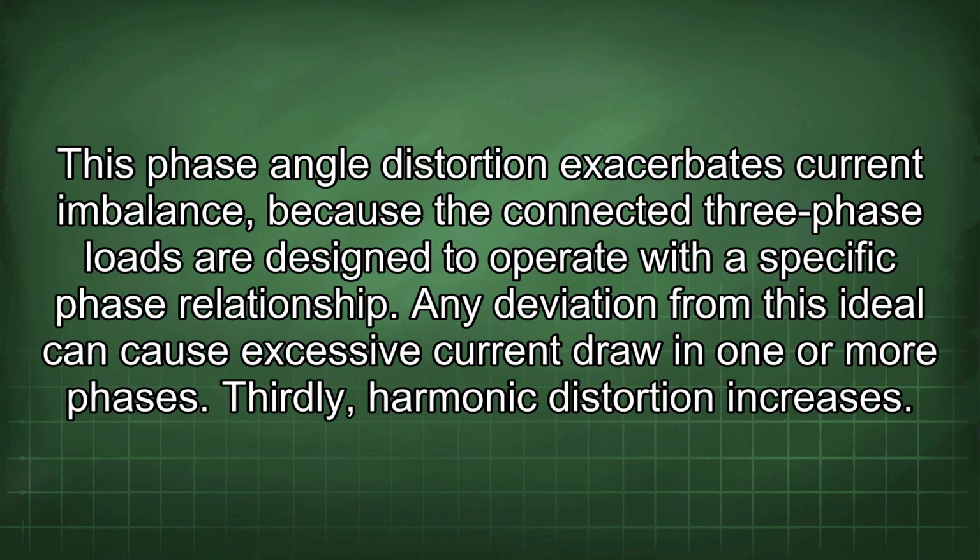This phase angle distortion exacerbates current imbalance because the connected three-phase loads are designed to operate with a specific phase relationship. Any deviation from this ideal can cause excessive current draw in one or more phases.